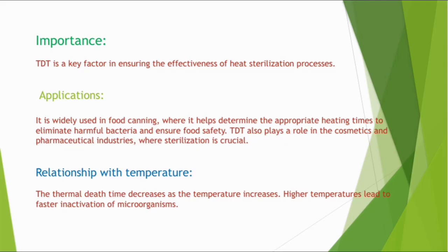Now, moving on to applications. TDT is widely used in food canning. It helps us determine the right heating times needed to kill bacteria and keep food safe for consumption. This is crucial for preventing foodborne illnesses. TDT also plays an essential role in the cosmetics and pharmaceutical industries, where sterilization is absolutely vital to ensure product safety and efficacy.